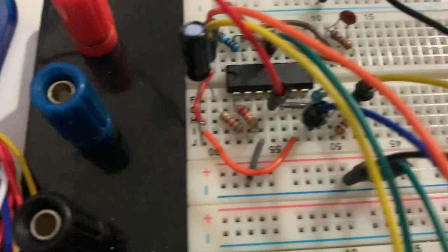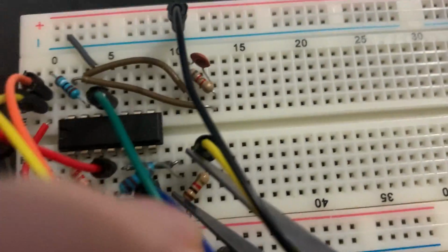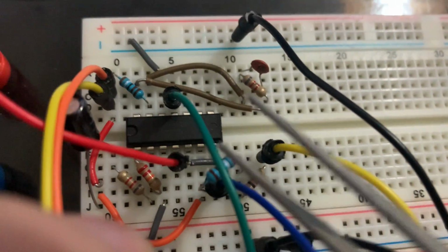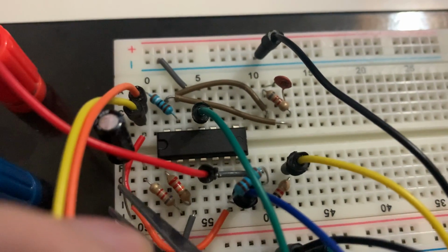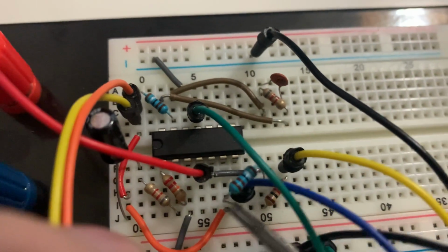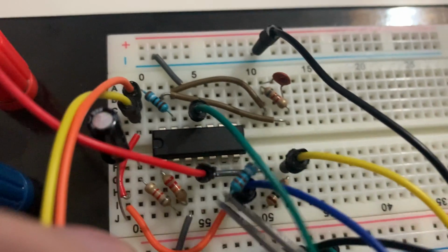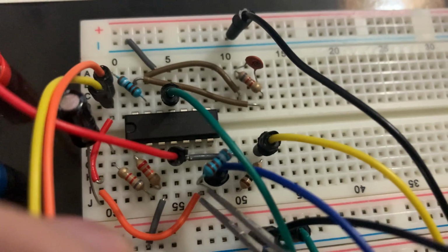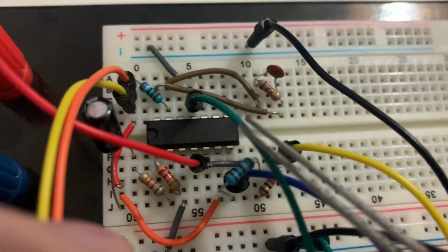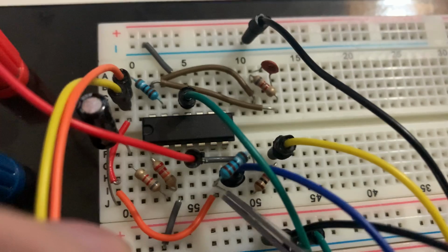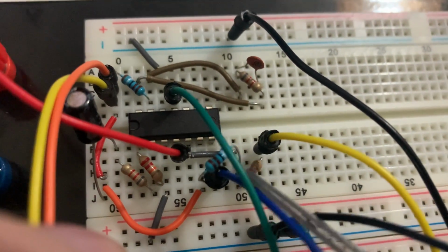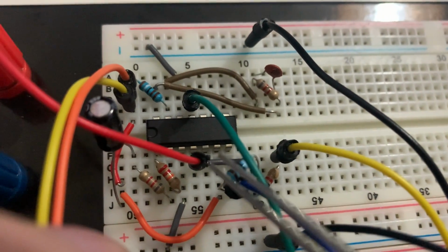And finally, the Schmitt trigger. So this part is the Schmitt trigger. As you can see, the signal input is connected to here, to the negative input of the Schmitt trigger, and the positive and the output is connected to this RF, which is a 5.5 kilo resistor, and then connected back to the negative input.